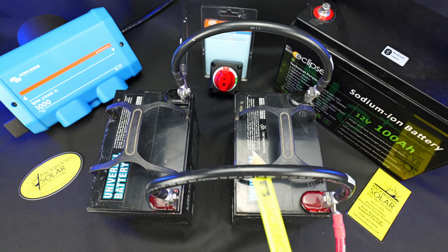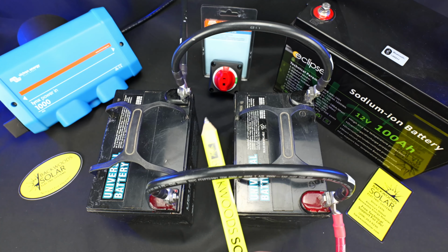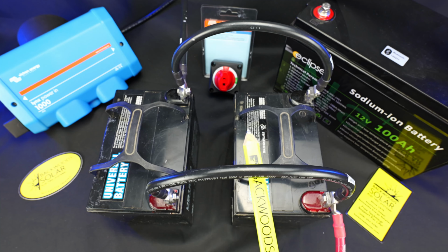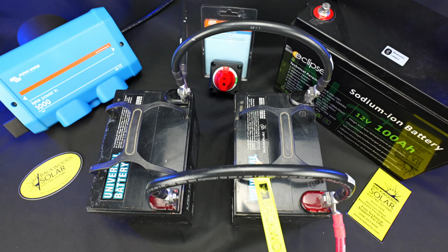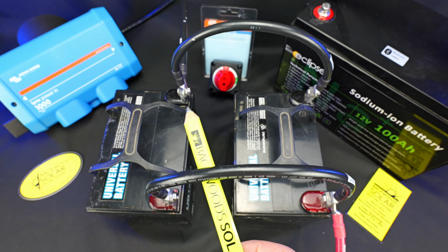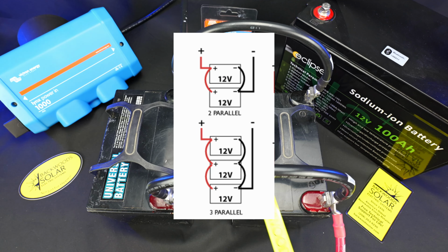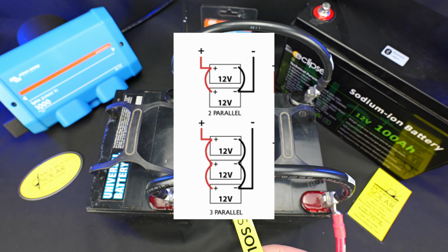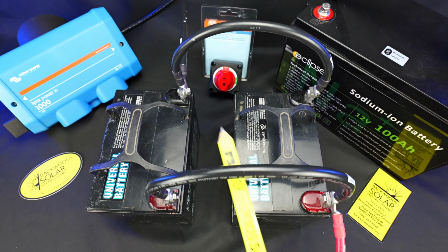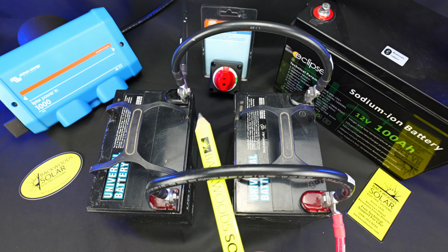Now, this is exceedingly important in any battery configuration, whether you're doing a parallel wiring configuration like this or you're doing a series configuration. You always want to leave from the opposite corners of the string or the bank. This ensures we get equal flow of energy out of all batteries within that string or within that bank.